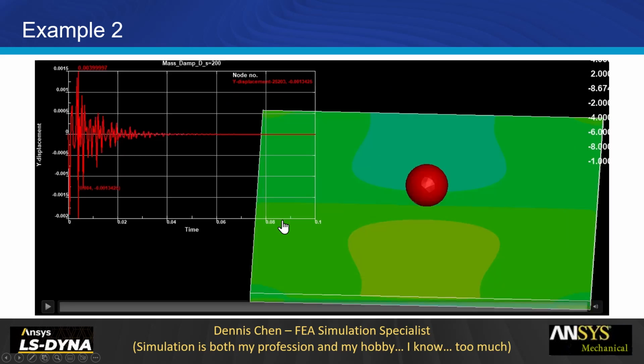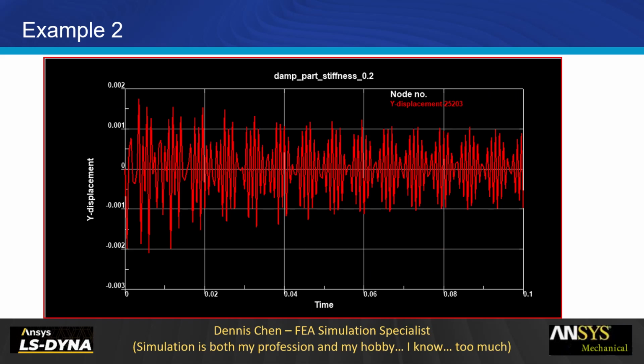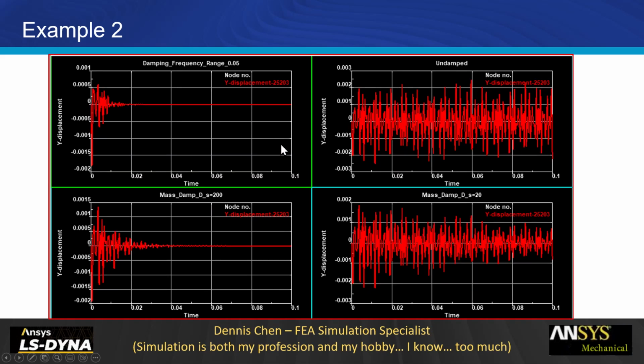So it usually requires a few tries to get the right amount of damping into the system, all right? And if you over damp it, you actually lose amplitude in your reactions, right? So you don't just over damp the system, you also lose some amplitude, because most damping is applying an additional force term in opposition to the nodal velocity, nodal accelerations, for example. So if you over damp the system, you also lose the peak amplitude, which sometimes is what you're looking for.